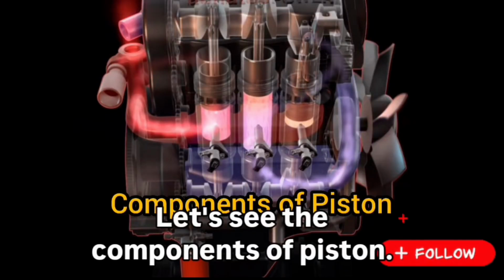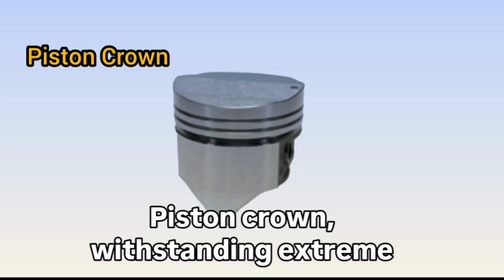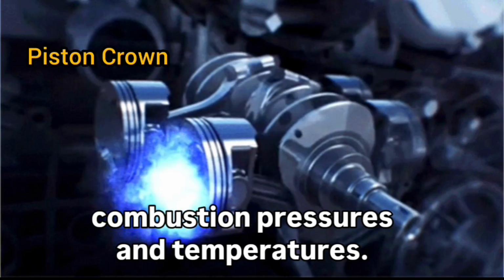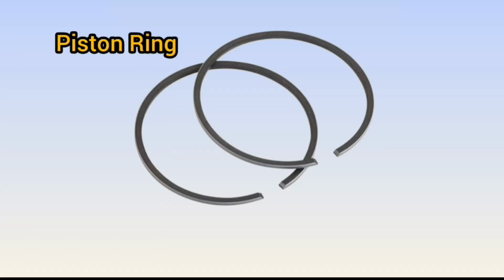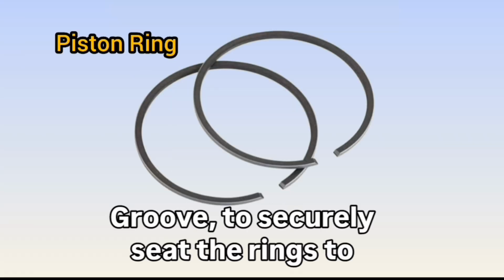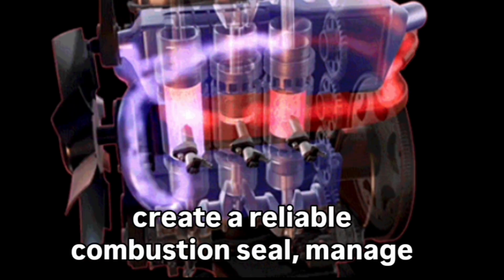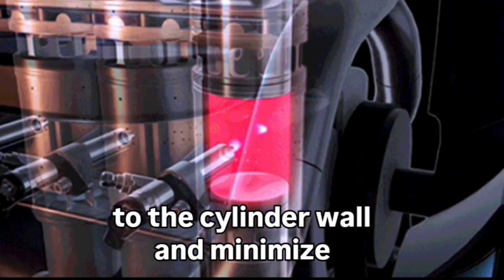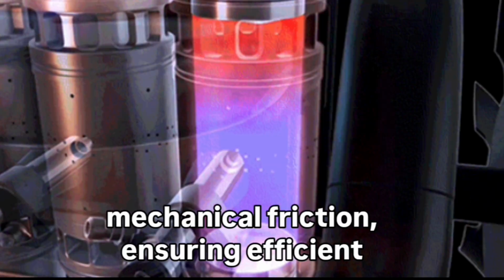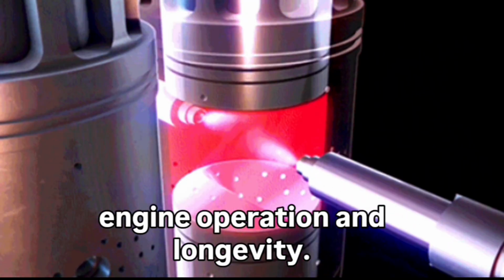Let's see the components of a piston. Piston crown, withstanding extreme combustion pressures and temperatures. Piston ring groove, to securely seat the rings to create a reliable combustion seal, manage engine oil, conduct heat from the piston to the cylinder wall and minimize mechanical friction, ensuring efficient engine operation and longevity.